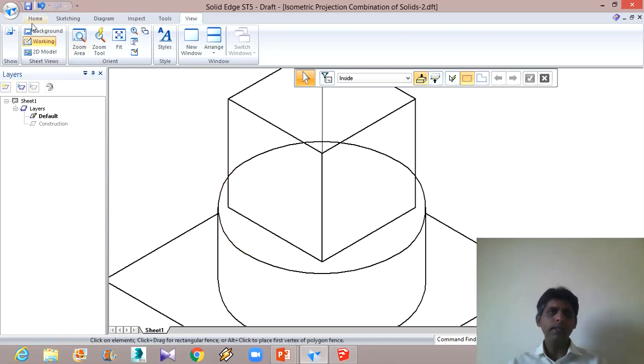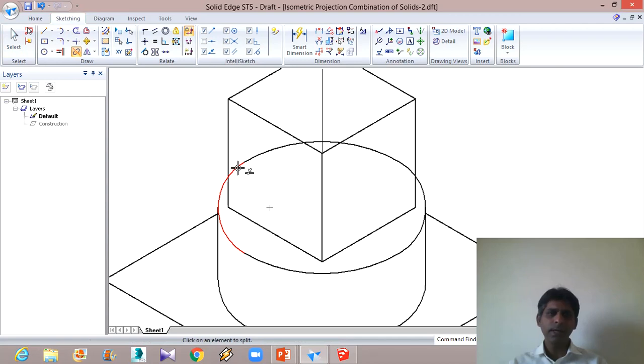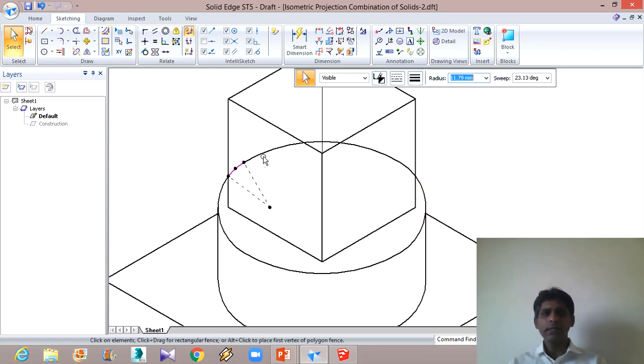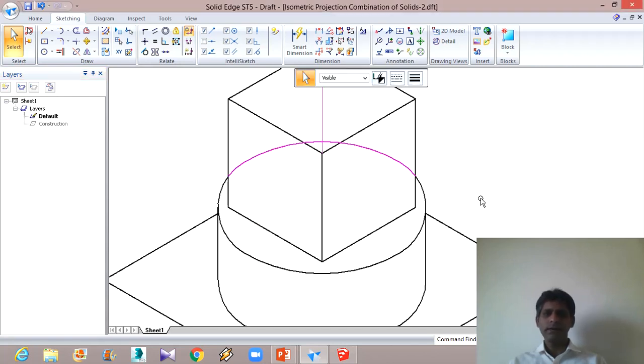So I will come back here. I will come back to sketching. I will select split command. I will select this arc and I will split it at this point, and I will select this arc and I will split it at this particular point. And now I will select all of these, and I will move them to the construction layer. I have just randomly named this. You can organize the layers properly.